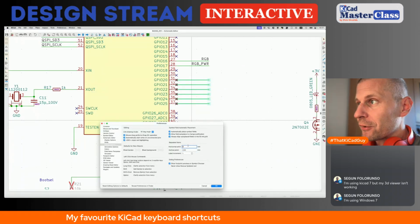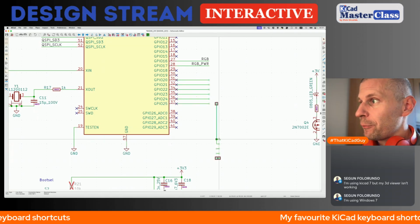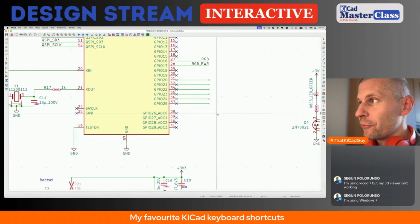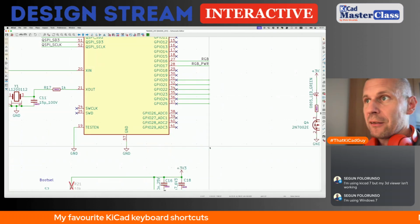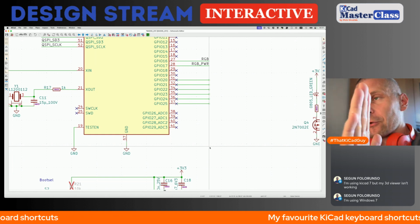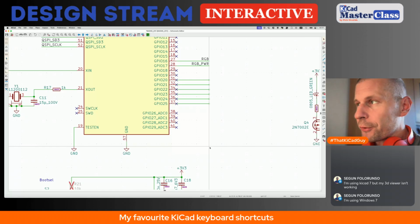You can edit the horizontal pitch, so it can work even for horizontal items. Because now it wouldn't work. But if you define the horizontal pitch and change the vertical pitch to 0, it will go sideways, not from top to bottom.